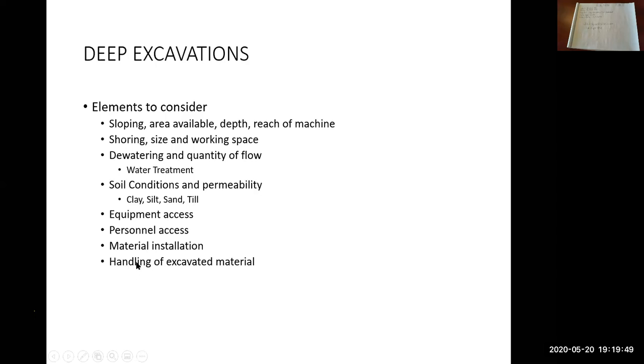So that leads into the materials here. So the last one there, handling excavated material. So with your deep excavation, if you have an excavator on the top, so at say road surface, can that excavator reach the bottom? If it can, then likely that excavator can remove the material from the bottom. Now it's likely that that excavator, if the hole is big enough length and width-wise, can't reach the middle. So you would more than likely have to bring in an excavator and fly it in with a crane.